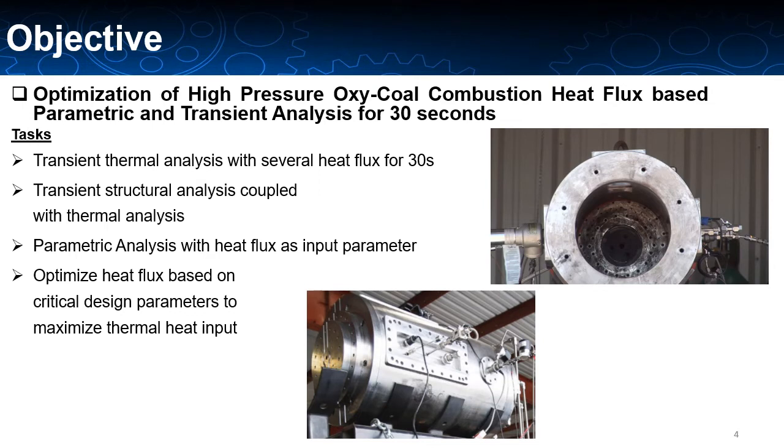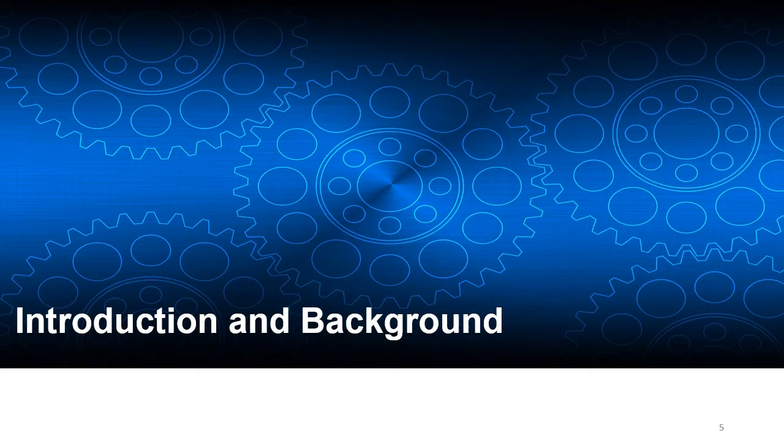Then the result was coupled with the transient structure analysis, and heat flux was used as input parameter. The value of the input parameter was varied to find out the maximum heat flux that we can have that will also meet some critical design parameters.